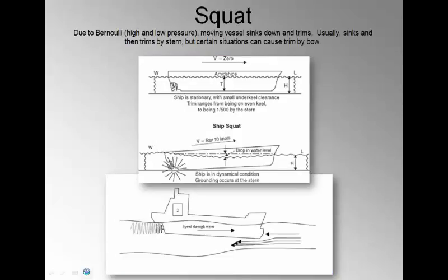Squat. Squat is the exact same thing as bank suction, only it happens on the bottom. As I transition from deep water to more shallow water, the hole that my ship is leaving in the water has to be filled more quickly again, and I don't have as much volume for the water to quickly fill in that hole that was left. So that means water has to move from up forward and then come in here, or from back aft and come in, which increases its velocity and therefore lowers the pressure and is going to cause a suction effect in that direction, which you can see here can end up with you touching bottom.